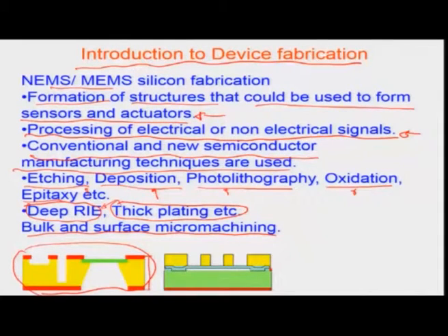This T right here is the thickness of the wafer, and we are seeing material being taken off subtractively from different regions of this particular thickness of the silicon wafer. So, any such process which involves subtractive machining, where material is taken away at the micron scale or the microscopic length scale, is better known as bulk micromachining.